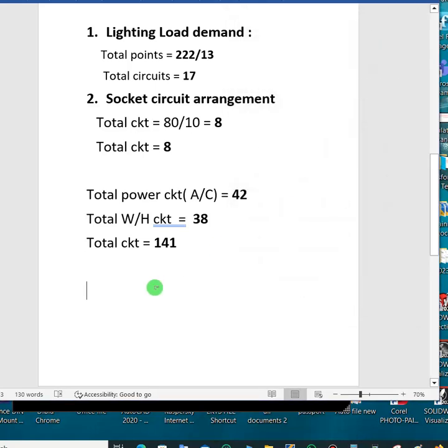That is for the protective device. Now remember that when we are providing 6 spare breakers in each of the distribution boards, the lighting point is going to be given priority. So lighting is going to have 2 breakers out of the 6: 10 amps times 2, two pieces of 10 amps left unused.